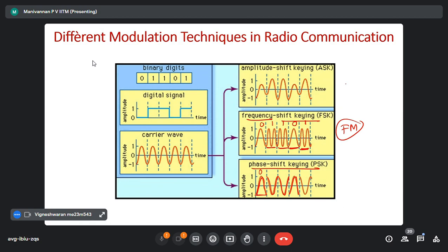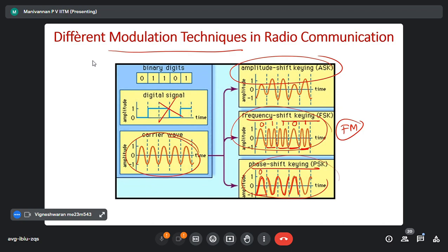So Bluetooth, Wi-Fi and ZigBee may use amplitude shift keying or frequency shift keying or phase shift keying, which is called digital modulation. Please note that again, data is not transmitted directly. Only the high frequency carrier is transmitted. What is the carrier frequency? In ZigBee, it is 2.4 gigahertz. Very high frequency. Correct? That's why in your vehicle to vehicle communication, the antenna is like your cell phone, invisible, very small, a few centimeters. Okay.